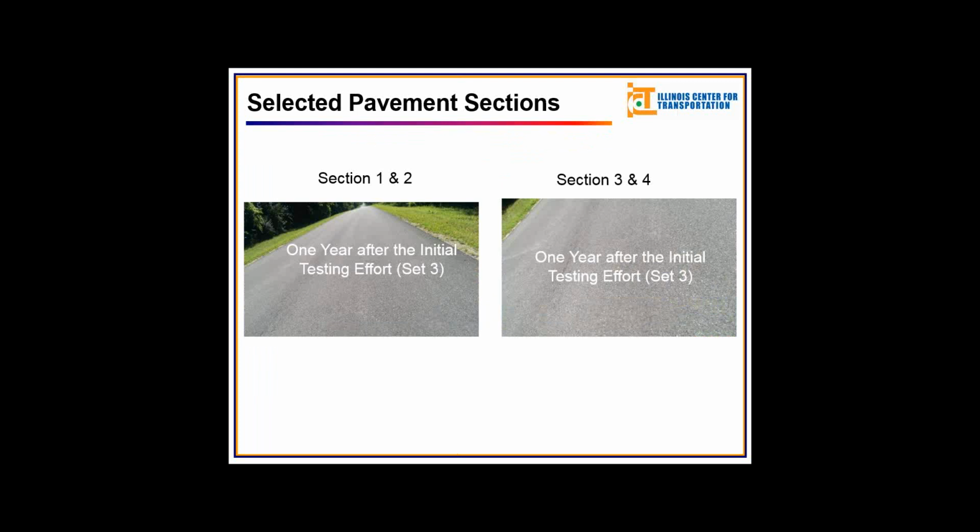Mazer asks a question online here, and he would like to know, how do you consider the asphalt mixture properties as well as viscoelastic properties depending on the temperature of the pavement on the final overlay design? Well, at this point, we are just assigning the moduli values, so we are not considering the temperature variations or viscoelastic properties.